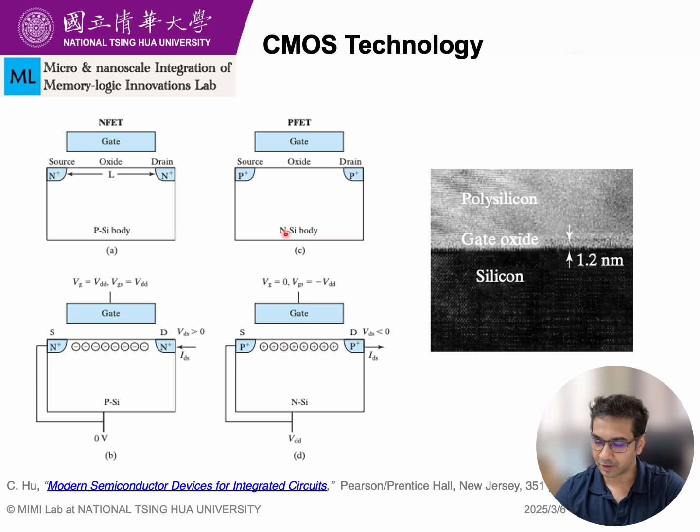also the doping concentration and type. You also have to ensure how and when you will dope, like whether you want to dope the P-type first or N-type first, and how you want to isolate the N-type region while doing the P-type. You have to think of everything together, so it's not that easy. It's very tedious and time consuming.